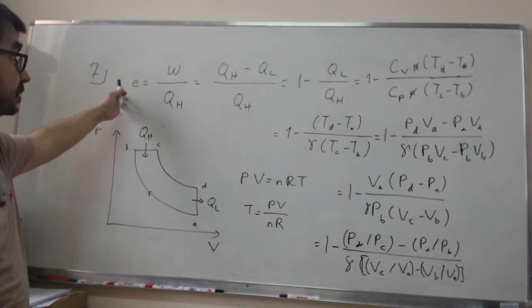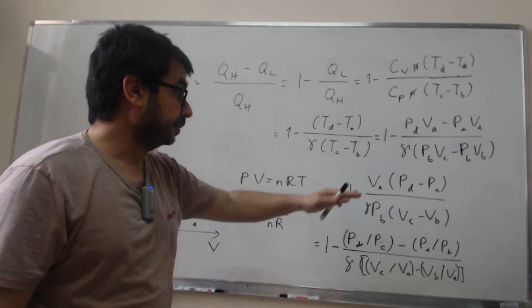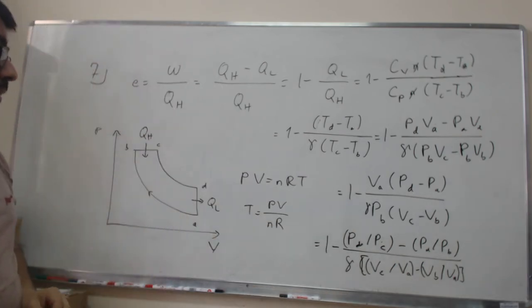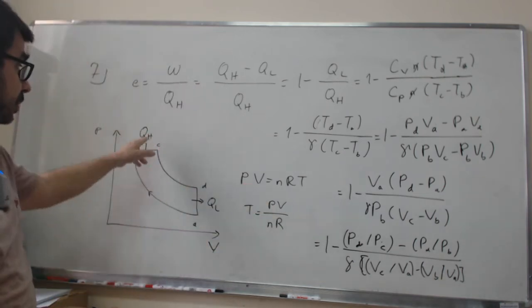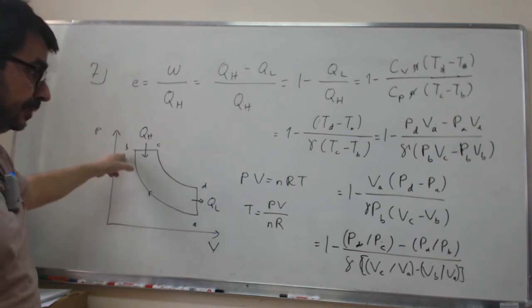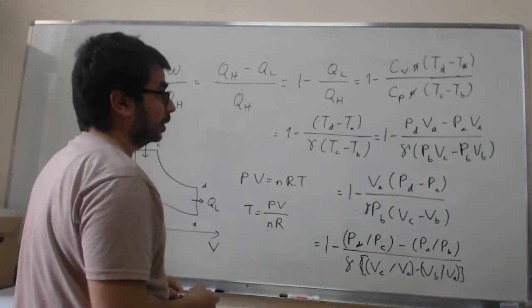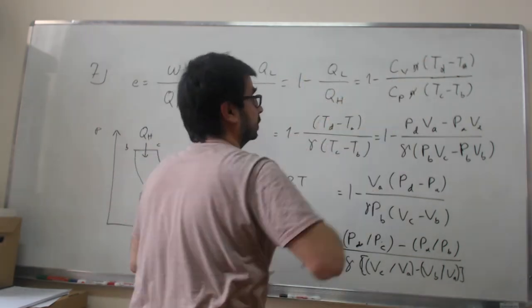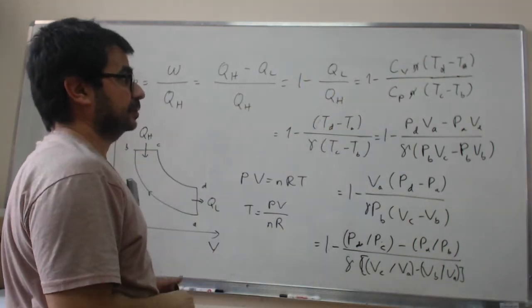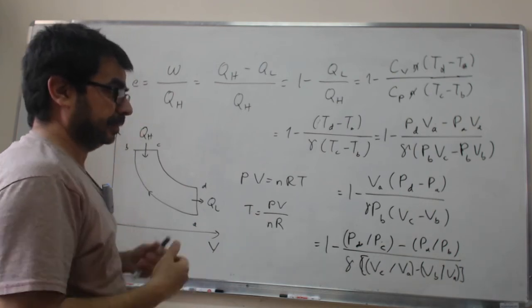You start with the definition of efficiency, and then you manipulate this a little bit to make things look dimensionless by making appropriate arrangements, and then you turn this into some connection over the adiabatic paths. Then you use the adiabatic expansion formula, and that thing comes out. Perhaps one thing that's not trivial to see is writing it in this form with the specific heats, and then writing the ratio of specific heats in terms of gamma, so you get something easy to manipulate. But let's look at the other problem.